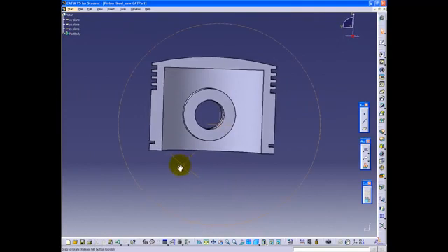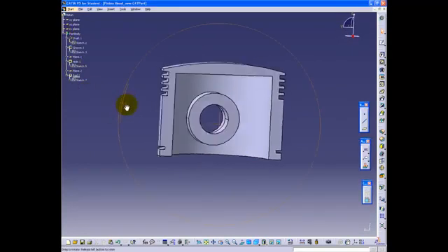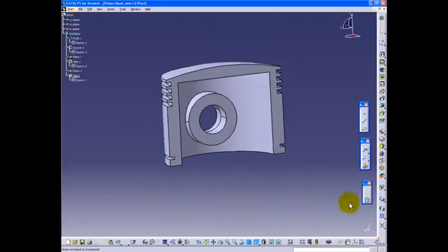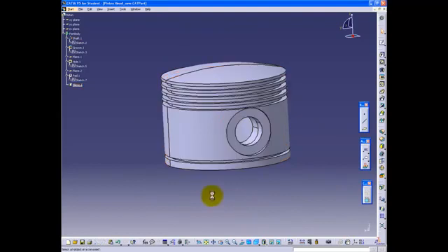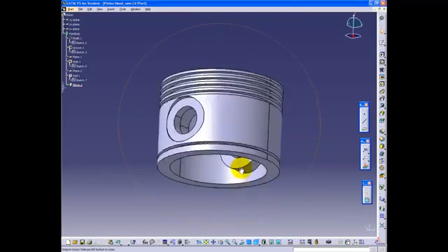As a beginner, it is important to always double check your work as you move along. Finally, use the mirror command on the part and select the YZ plane as your mirroring plane. And if you follow these steps, you should now have the piston head complete as shown.